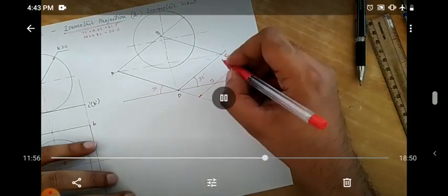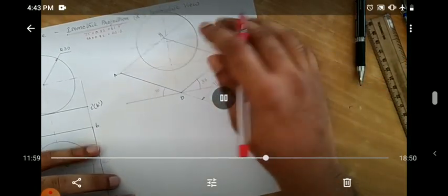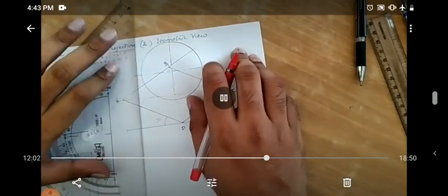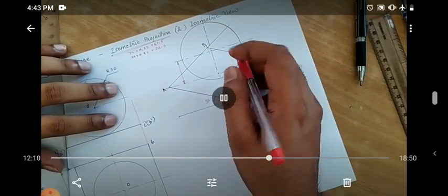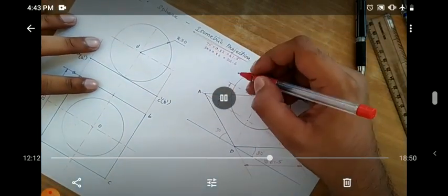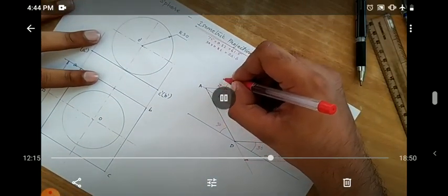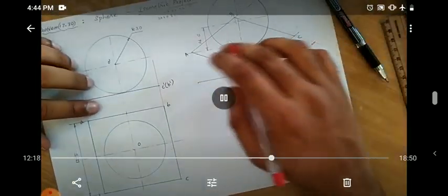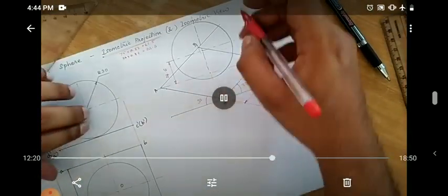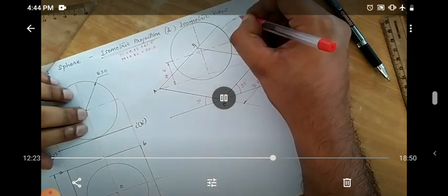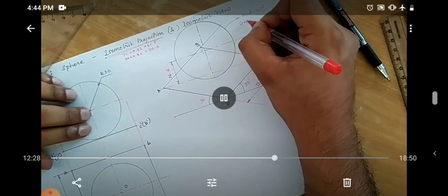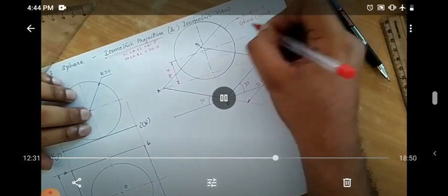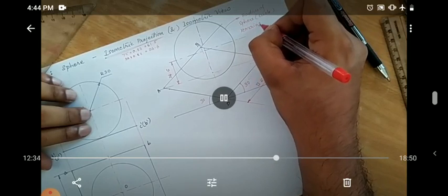See, the edge DC, or the edge of that square, is now 61.5, and the height of the center of the sphere from the center of the square lamina is again changed to 24.6. 30 multiplied by 0.82 is 24.6, but the radius of the sphere will remain as 30 itself. This is a special property that applies only in the case of spheres. That means the isometric projection of a sphere will have the same radius.